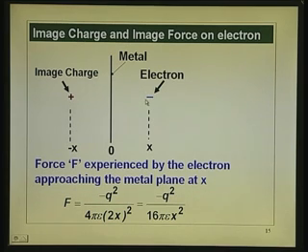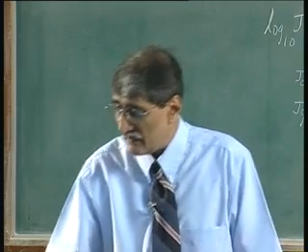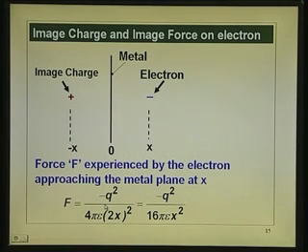So, you can compute the force due to the induced charge here by putting this image charge. What is the effect of that? That means there is an additional field coming up. When you take a look at the energy band diagram in thermal equilibrium or under forward bias conditions, what you plot there is due to the built in potential, due to applied voltage, etc. What we are talking of is apart from that. Due to the image charge, there is an additional force. I do not have to explain this particular term.